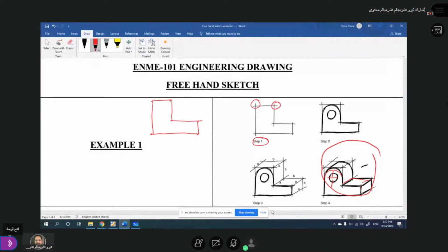But remember, this is not a thick line. This is a thin line. So use two pencils. Use the H or 2H pencil first to draw these lines. Okay. Easy. Once it is done, now what you have to do is draw the circle and the semicircle here. So what should I do in order to draw the semicircle? Okay, first I will mark it because this is at the center. So I draw a line at the center. Okay, then another line I draw at the center.